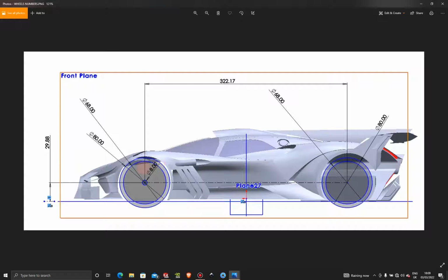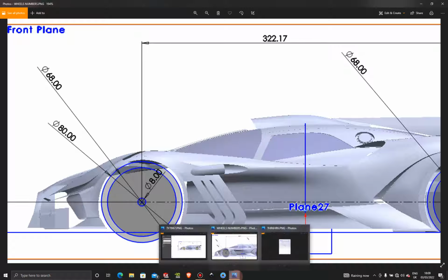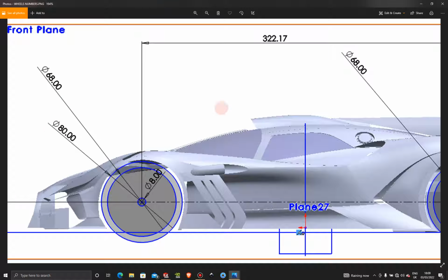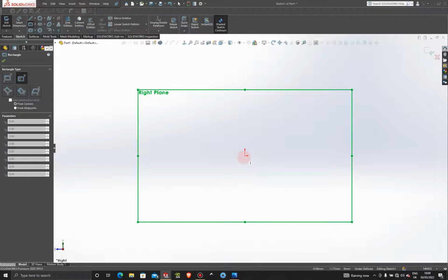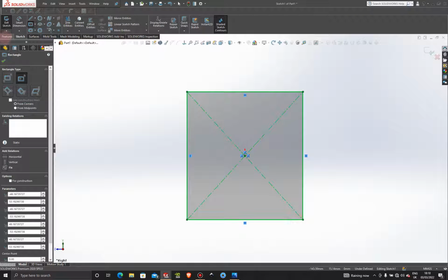Okay, so first we're going to have to make a center box, and first we're going to create a rim. The box is going to be 68, and the width of the tire, the wideness of the extruded tire, the rim is actually going to be 51. All right, so let's create the 68 box first on our part here. So let's grab a center rectangle and drop it right over here on the center, just a square like that.